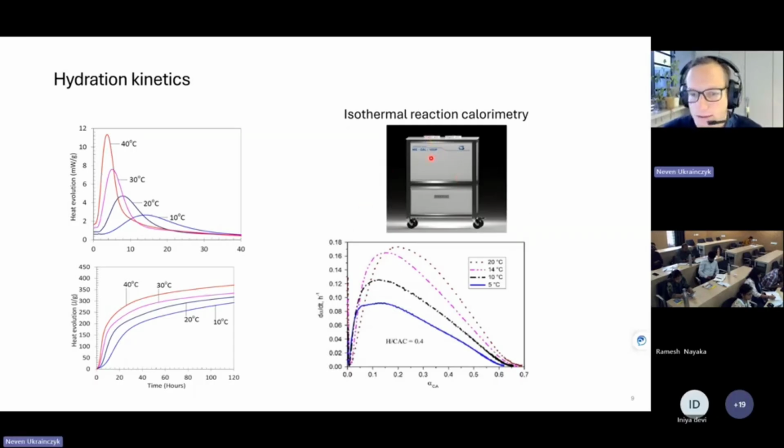You have inside the thermocouples, which measure the temperature difference. And from the temperature difference, you know the flux. You keep your sample isothermal. And from the flux, which is the heat flux, it's the milliwatts. So it's joule per second. That's the flux. You know how much energy was released.